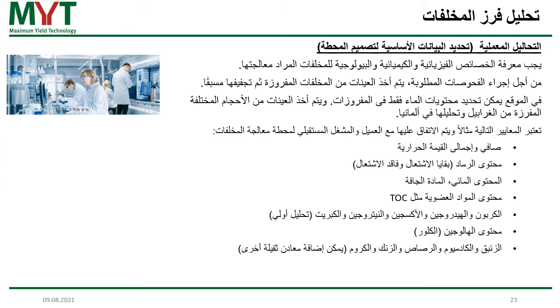What are you going to determine in the laboratory? The laboratory analysis is for the physical, chemical, and biological properties of the waste. For the investigations, the samples are taken from the sorted waste, and then they are pre-dried. On site, you can only determine the water content with the drying cabinets, and from the different sieved fractions, of course, the samples will be taken to Germany and analyzed.